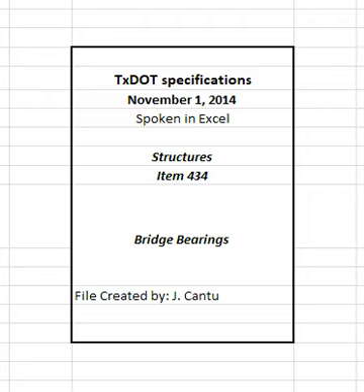3.3.3 Storage. Store HLMR bearings horizontally in a dry, sheltered area. Provide moisture and dust-resistant wrapping maintained in good condition until installation. Lift bearings only from the undersides. Protect bearings from damage, dirt, oil, grease, and other foreign substances.